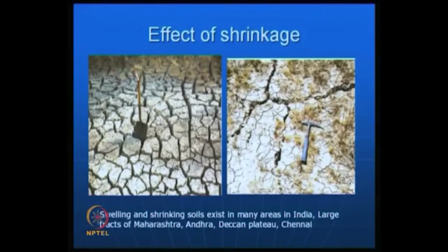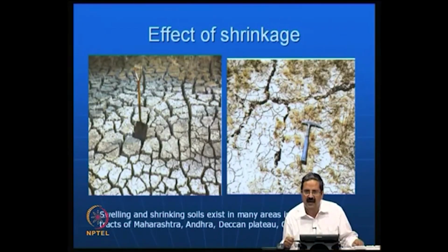So, what happens is that under these influences you have a lot of shrinkage problems, and this is essentially because the soil has big variations. Water content can be 100 and it can be 10 also, which is something that one needs to take care of. So, what we do sometimes in these cases is add some treatment, like some sort of lime and other things, where the liquid limit water content from 100 can come down to 50, and the shrinkage limit can come down to 20. So, with that the water content range is 50 minus 20, which is 30%, as opposed to 90% in the previous case. That is essentially a ground improvement technique.